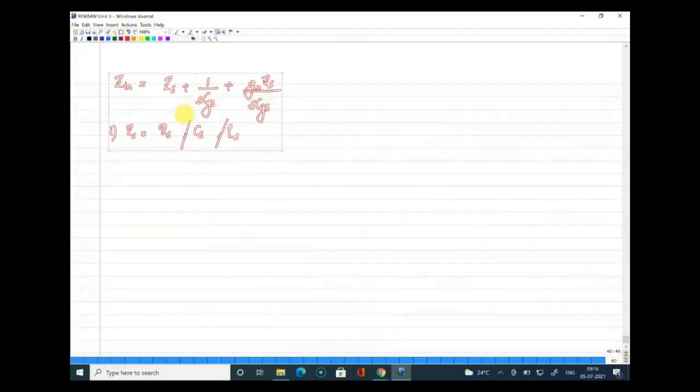So this is the impedance we got from the discussion on CS with degeneration, and let us look at the input impedance one by one. The first case we will consider is substituting ZS as a resistance. Even before substituting a resistance there, we know that resistance will definitely add noise. But before dismissing that, we'll just consider it and see what the effect is, and then we will